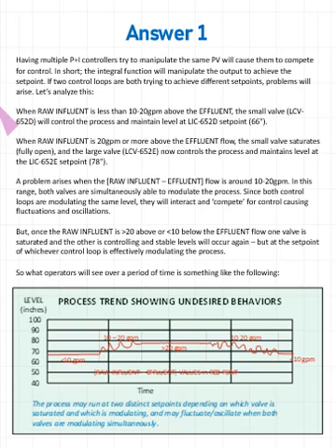I looked at this process for a really long term, many months, and this is exactly what happened over a period of time. Stable at the low set point, stable at the high set point, stable at the low, oscillations. It would fluctuate back and forth. Sometimes it would oscillate in the middle if it was at that imbalance level for a long time. But it's very easy to pick up on a long-term DCS history.